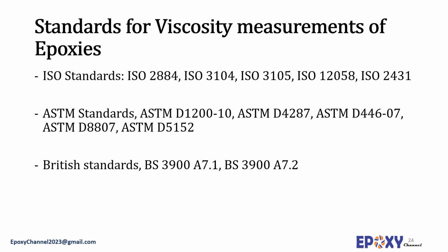ASTM D1200 presents the Ford cup viscosity measurements. ASTM D4287 is high shear viscosity and is a cone and plate method. ASTM D446 is the capillary based method. ASTM D88 is the standard procedure for the Saybolt method. ASTM D5125, this is the standard for the ISO cup method.